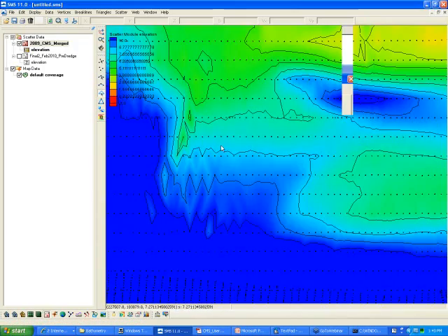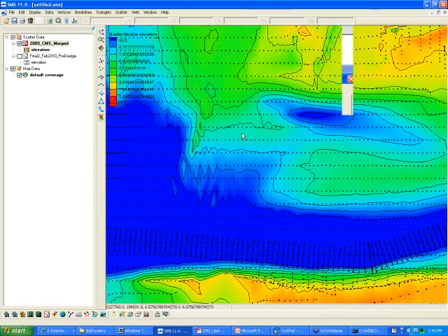Another issue I commonly see with bathymetry is that people, just because you have bathymetry with high resolution doesn't mean you should use it. The reason for that is high resolution bathymetry, like the divider, has a lot of detailed information that you don't necessarily want the model to have. For example, bed forms.